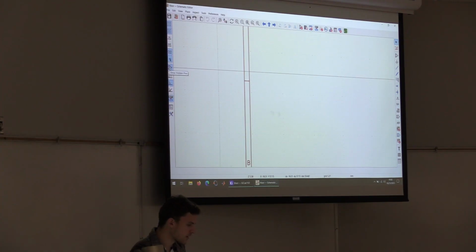What do we got here? We've got hidden pins on schematic symbols. Depending on how the footprint is, you might have hidden pins on there that aren't used in the schematic but are used on the footprint, and to make it functional in the software, you've got hidden pins. If you need to see those, you can select that. Otherwise, it's generally not needed.